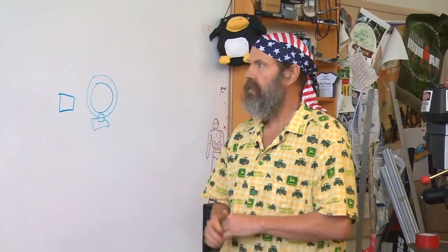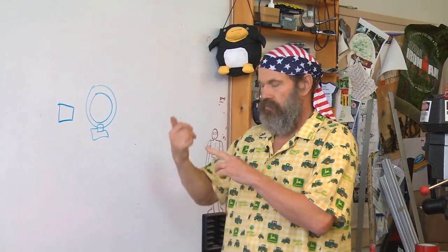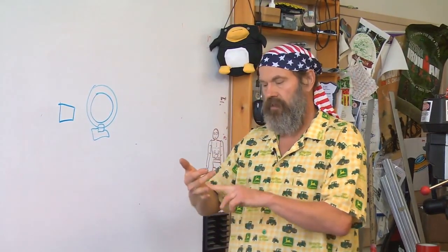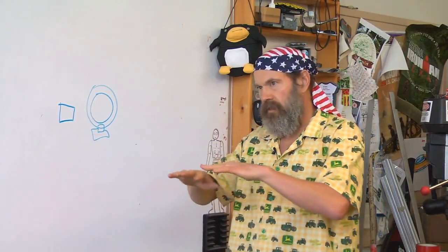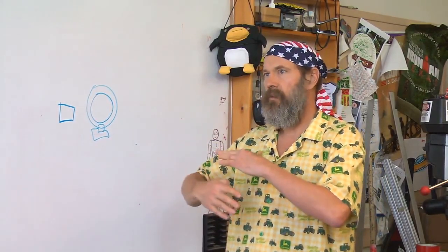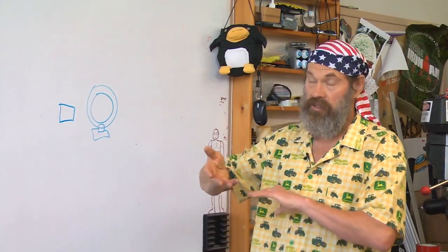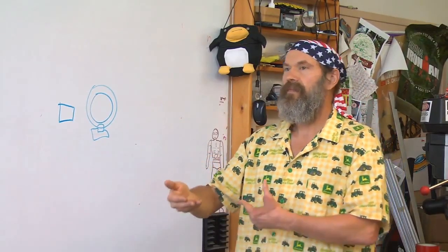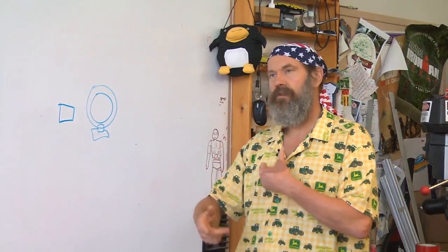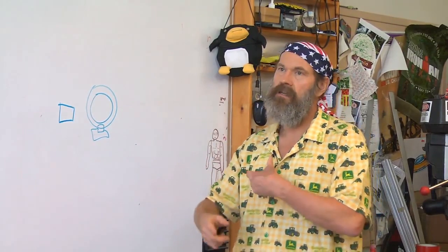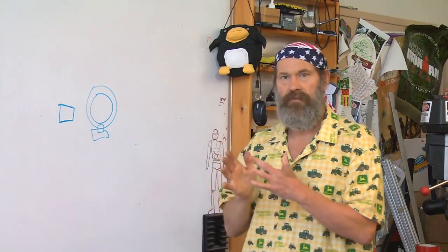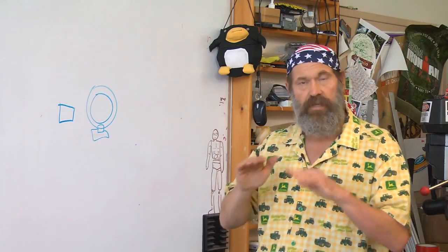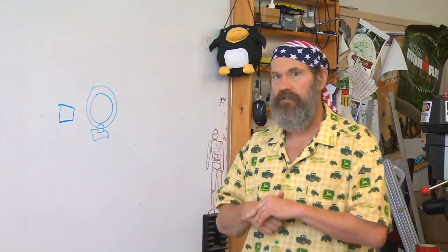Okay? So remember, Fred Park, structure loop, the stick figure sketch, start to fill in the motions, do the reciprocal of what you think you want to check the opposite design. The sketch looks good with your first order calculation sizing, finite element analysis, build the bench level test, verify, then you can commit to a real solid model and start to do your production drawings.